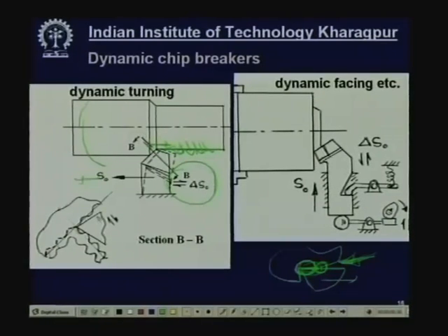Here you see that this cutting tool, if you take a section along the orthogonal plane, this is a chip flowing. So, this is oscillating. So, this is the path. The previous path was like this, it was oscillating, and now it is going to cut in this direction, not a straight path, because it is oscillating. Now, these two waves, the wave already cut and the groove going to be cut, may be aligned or may be offset by 90 degrees or any degree.